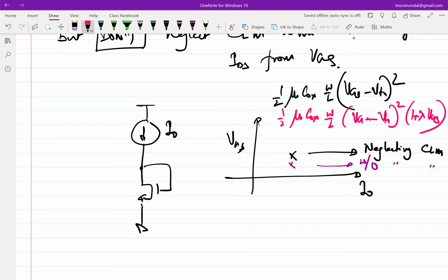Right. So that's why, in the purple case, for the lower value of VGS, you will get the same value of current. But this is particular to this configuration. Right? If the configuration changes, then the curves can also change, because all those curves that we initially drew are for a certain value of VDS. Right? So VDS was a parameter. Right? So now it matched up two of the scenarios.